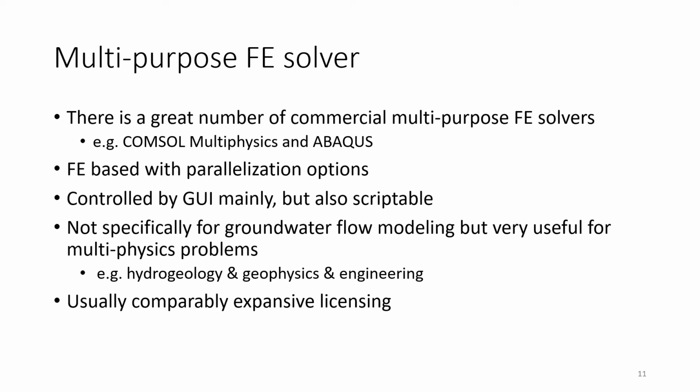It comes with a nicely controlled graphical user interface, allows you scripts if you desire, but it's absolutely not necessary. You can control everything over the graphical user interface. You have to pay attention because it's multi-purpose, so you often buy something like a core program, and then depending on what kind of physics you additionally need, you have to buy extra packages, for example, for groundwater flow or things like this. Again, it's not specifically designed for groundwater flow, but most of those packages or software are usable to simulate groundwater flow. And again, it's especially interesting if you want to couple it with multi-physics problems.